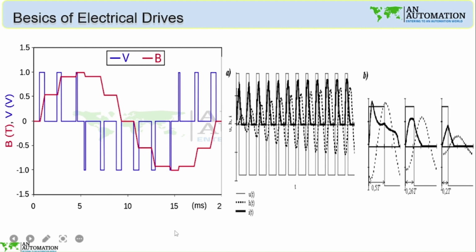When the bandwidth is small, that means we open the IGBT for a small time, and then the IGBT puts out a lower voltage. In the higher section of the sinusoidal, when the voltage level is high, we have to keep the IGBT on for a longer time. That's why the pulsating square wave is more open there.